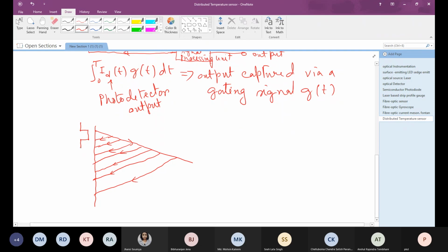Now, if this is say 1 millisecond, is the next pulse that has been launched. So therefore, during this 1 millisecond duration, all such shifted pulse phase trigger will be generated, and that will be fed to the integrator.